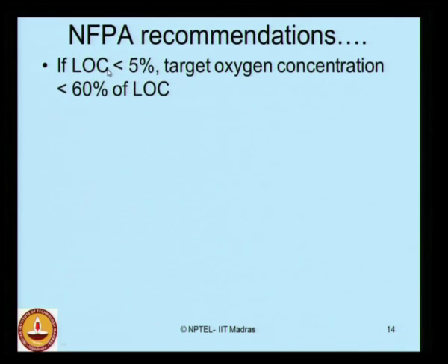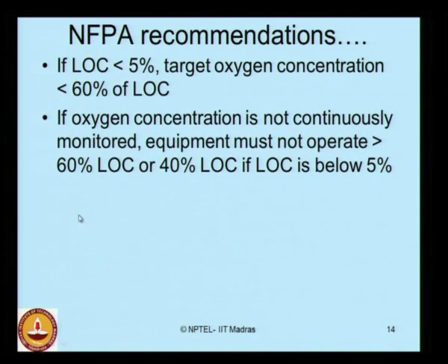If the LOC value is less than 5%, then the target oxygen concentration should be less than 60% of LOC. Please remember, limiting oxygen concentration is different from the target oxygen concentration of the storage vessel.